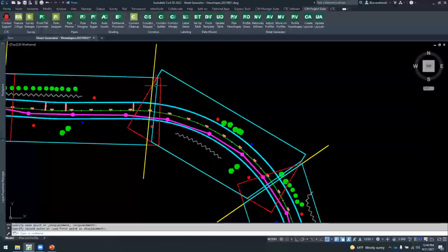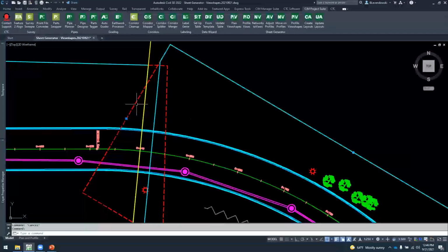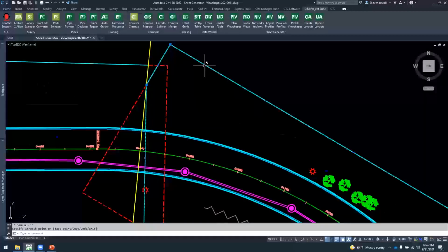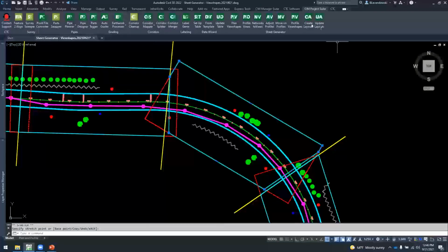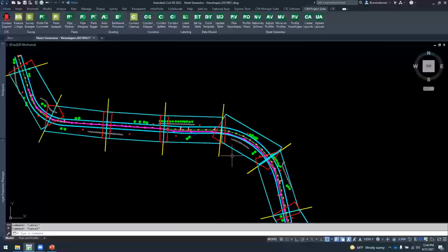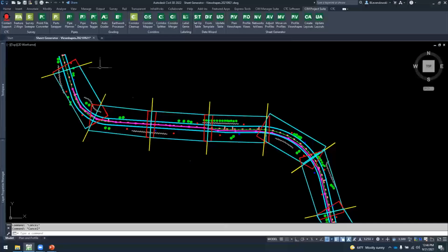You want to tweak that a little bit, move the entire print block, that's the representation in my sheet, and then the viewport itself will be this thing right here. So you can adjust that however you want. And when it comes time to creating layouts, the viewports will be modeled exactly after that. So there's manual tweaking you can do after the fact, or if you run it like this and you decide,